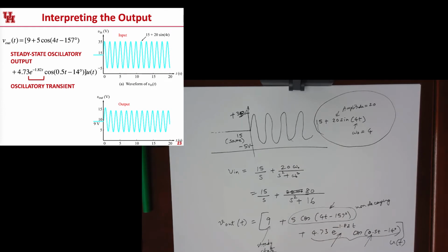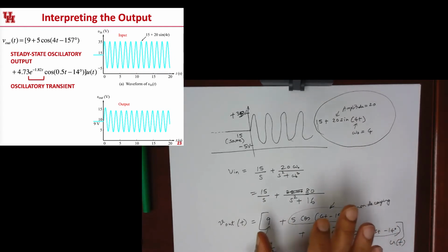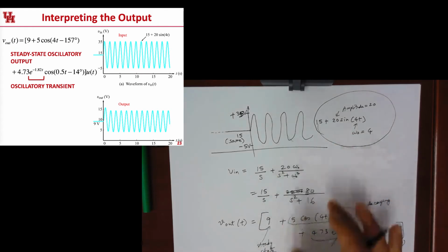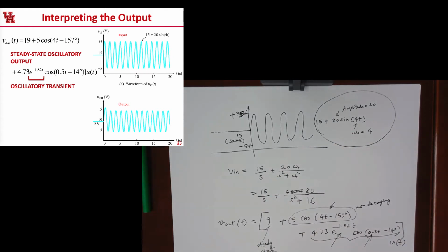right? So since the forcing in this case is oscillatory, we know for LTI systems that the forced output will also be oscillatory at the same exact frequency. So this is pretty clean except for this little transient part, and we have to make sure that this is well behaved. It dies off quickly and nicely and doesn't blow any parts.